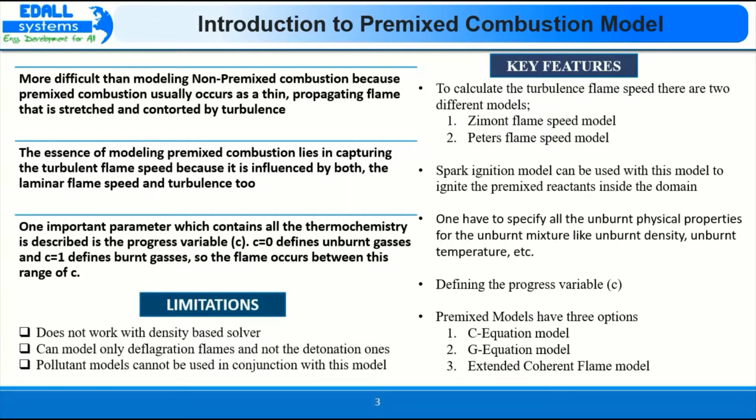Some of the limitations for this model are: this model does not work with the density based solver. Also, pollutant models cannot be used with this model, and this model can be used only to model deflagration flames, that is subsonic flames. We cannot model detonation using the premixed combustion model. So this was the complete overview of the premixed combustion model.